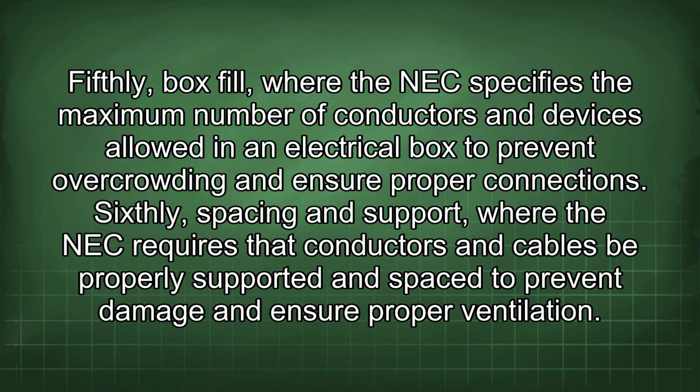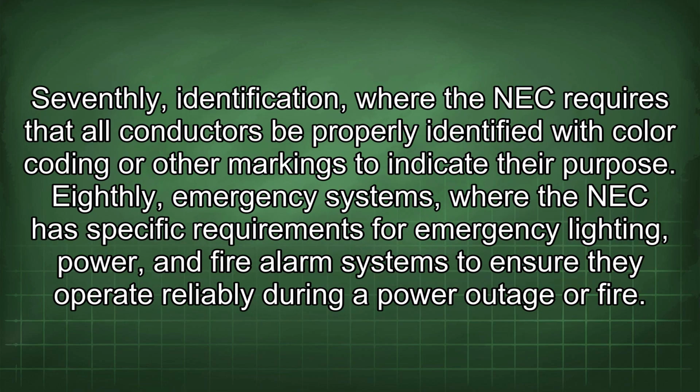Sixthly, spacing and support, where the NEC requires that conductors and cables be properly supported and spaced to prevent damage and ensure proper ventilation. Seventhly, identification, where the NEC requires that all conductors be properly identified with color coding or other markings to indicate their purpose. Eighthly, emergency systems, where the NEC has specific requirements for emergency lighting, power, and fire alarm systems to ensure they operate reliably during a power outage or fire.